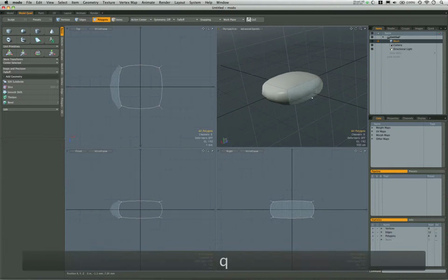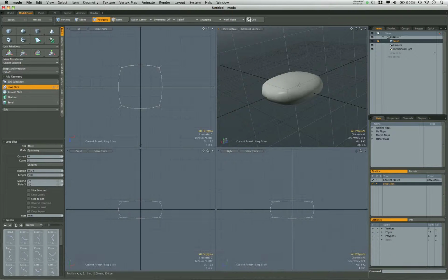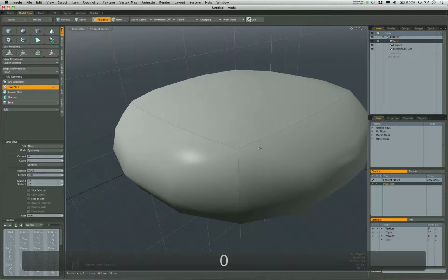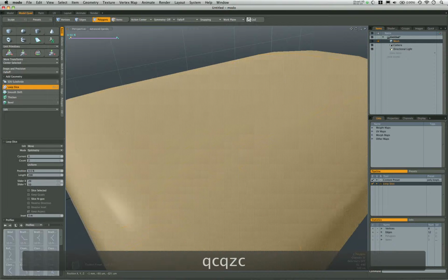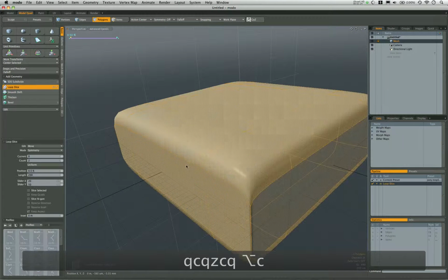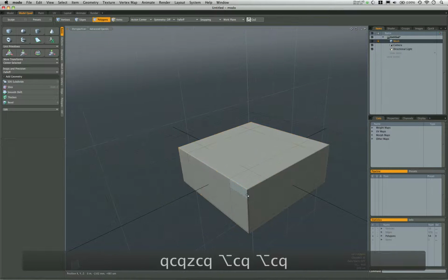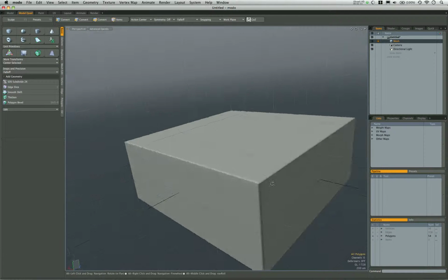So I'm going to drop my cube tool, and with Alt-C or Option-C, I'm going to start making my loop slices. Let's maximize this view so I can see all three corners here. Let's try this again, loop slice. Let's select our polys and then loop slice. We'll put in a couple this way, a couple this way, and finally a couple this way. And that now gives us, when you look, you can see this quad shape here on the corners. And this is what we're looking for.